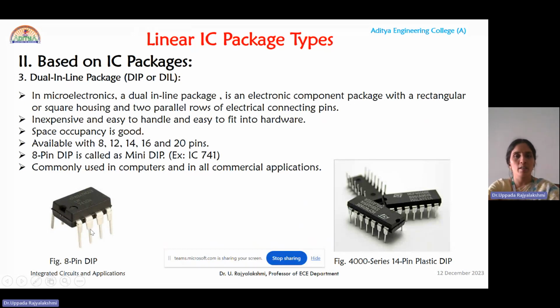So because of its structure, it can be easily fit into hardware. All these 8 pins can be fit into hardware at a time. So space occupancy is good with this dual inline package compared to flat pack. And it's available with 8, 12, 14, 16 and 20 pins. And this 8-pin dual inline package is also called mini DIP.